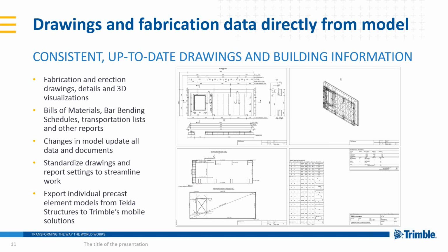One way to make drawings clearer to read is to separate the drawing into certain working steps, with only the information that is relevant for the person reading the drawing. For example, the group responsible for reinforcements has a drawing with only the information relevant to them, and the group building the shuttering, installing embeds, and other concrete inserts, like, for instance, in today's topic, the group using LAP laser projection systems, will only have information relevant to them in their drawings. Like this, the drawings will be clearer to read.